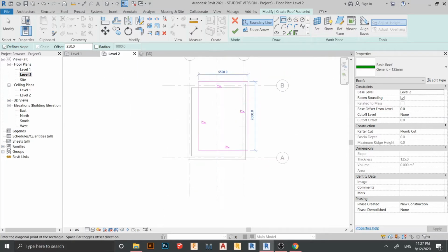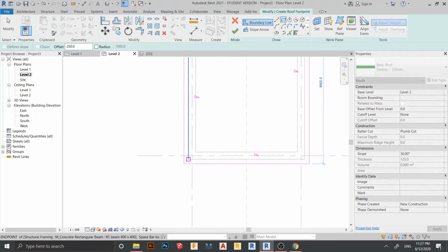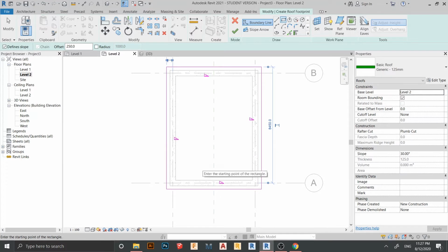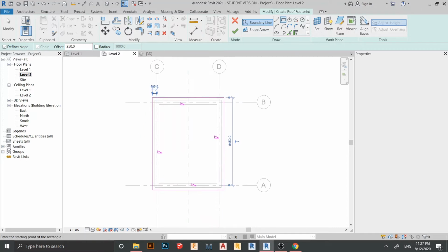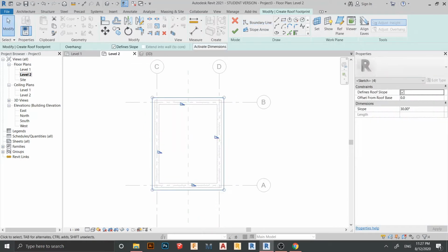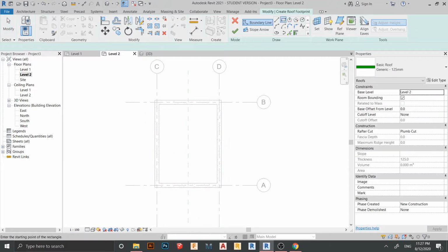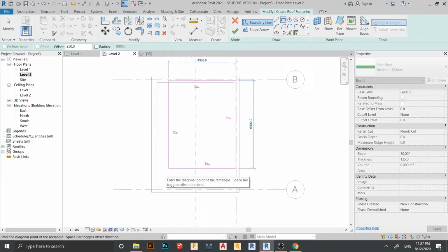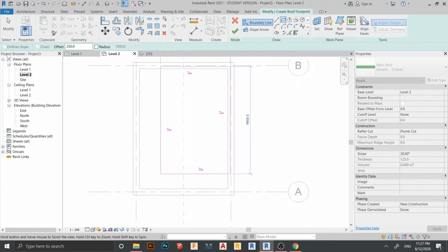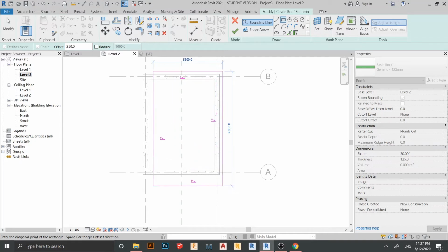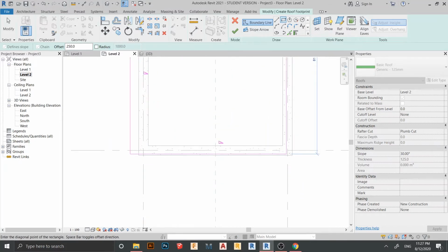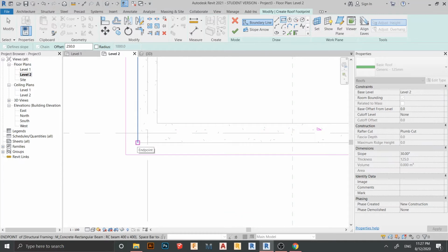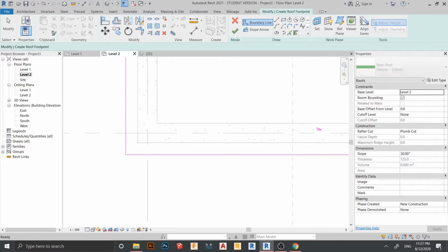Start from here one and here one. You can press the Tab key on your keyboard if your direction is going inside your roof. Let's say I give you another example. Let's say this one, then this one we go to 250 again, and then when you start to draw, your direction is going like this. To change direction, just use the space key on your keyboard, as you can see. So this one I change direction to outside, exterior. Hit escape a couple of times.